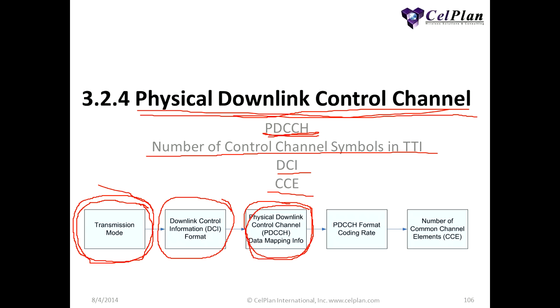It's 100% interference from the neighbor cells. So what 3GPP did, they allowed this channel to use a very high repetition rate. You will see that the repetition rate can reach 25 in a few cases, but it can also be 1.